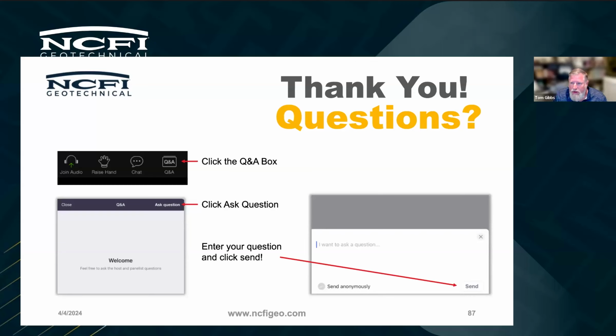So yes is the broad answer to that question. One thing that wasn't really covered too much in this particular presentation that I do want to cover is that quite a few of these products have the NSF 61 certification through ALS and Truesdale Laboratories. NSF 61 is basically the testing that's performed in order to say that a material is suitable for contact with potable water sources.